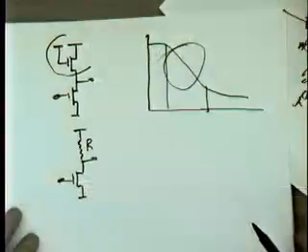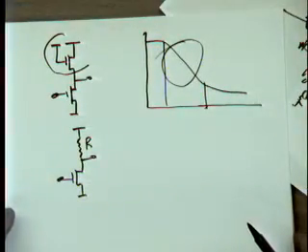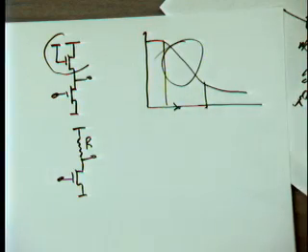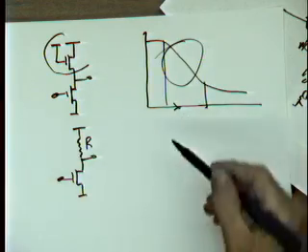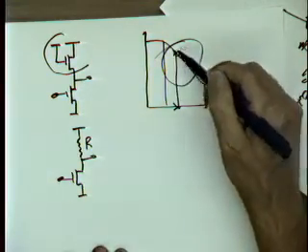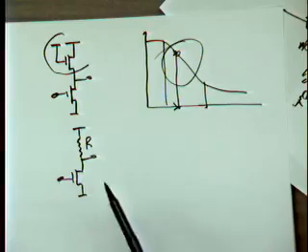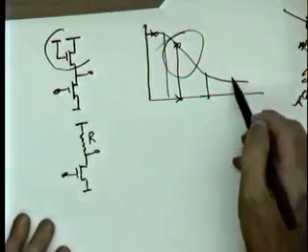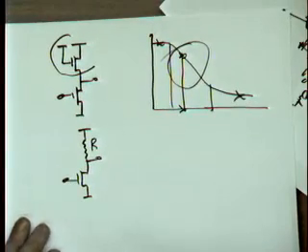Question: in the previous sketch, even if the input signal is above VIL, it can be regenerated too. It will be regenerative, yes. Even if you go into the transition region, the problem obviously is that I don't really know if it's going to be a 1 or a 0. It's kind of indeterminate. But if you go through enough gates, it's going to be for sure going back to the 1 or 0 regions, which is guaranteed.